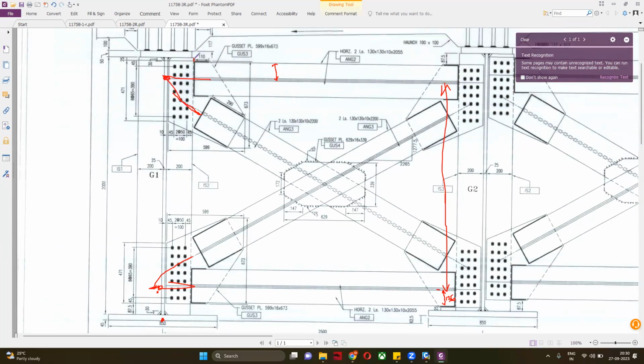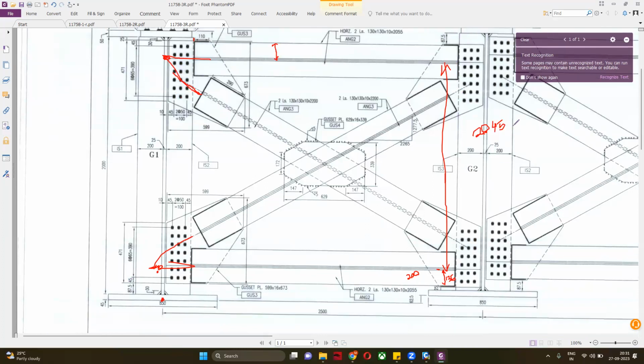Now here, if you look, the top is again changing, so we will create an equal one. We can even provide not 160 but 200 mm, that will be fine. If we use 200 mm, 200 bottom, 200 top, and this total height is 2000 and the bottom thickness is 45. So first I will minus this 45, then I will minus this 200, and then I will minus this top 200. So I will get this point.